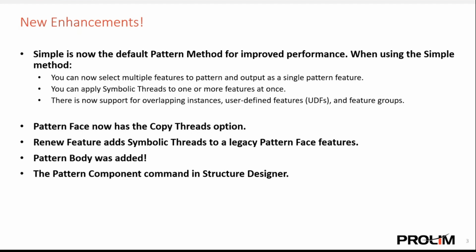The pattern face now has the copy threads option, similar to pattern geometry. It lets you copy symbolic threads to instance faces that look the same as the source face, which is useful for copy bodies in CAM and drafting applications. Renew feature adds symbolic threads to a legacy pattern face feature as well.